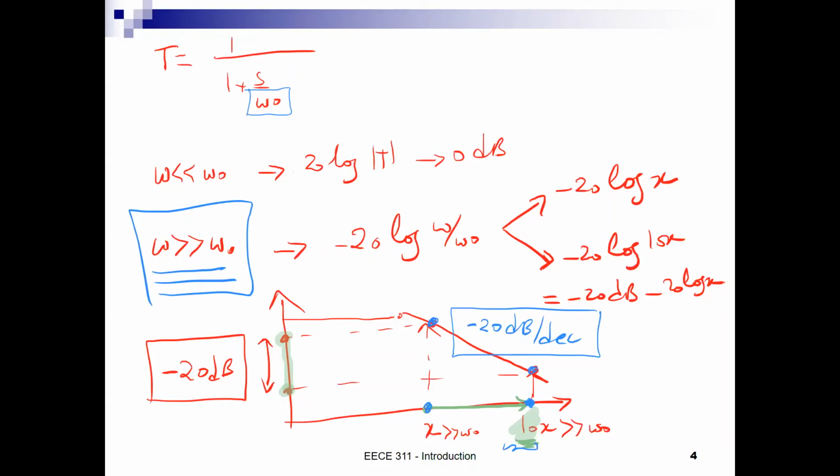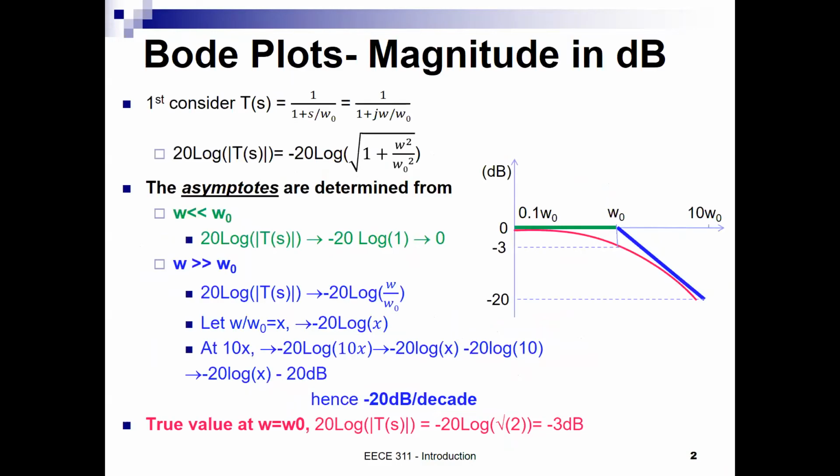Okay. So the summary which you will be using is as follows. We will put 3 points: omega 0 and 10 omega 0. Here I will assume I have reached a value which is much greater than omega 0, and anything below omega 0, we will assume I am smaller than omega 0. So the gain for this expression is going to be 0 dBs.